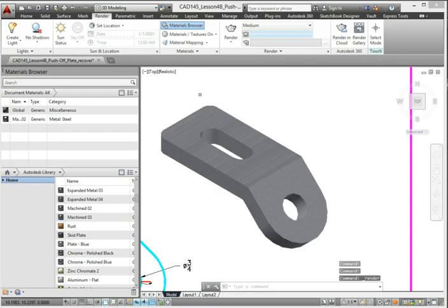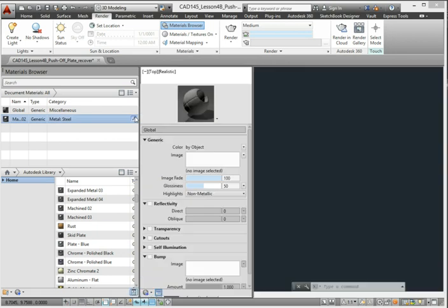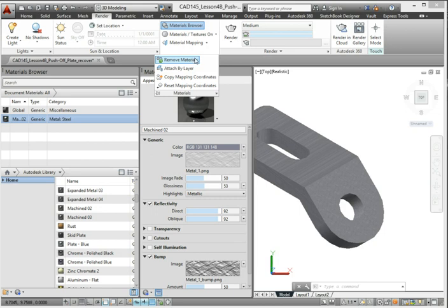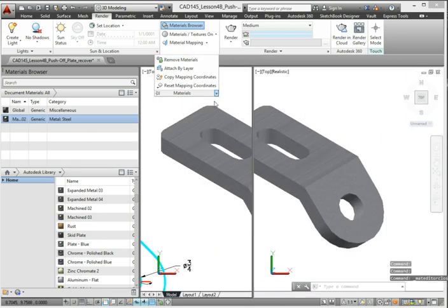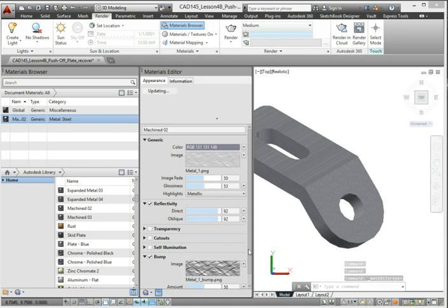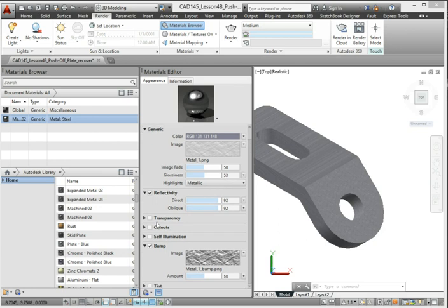Let's continue. If you edit the material settings, you'll get to the material editor. You can also get to the material editor here. We're clicking that arrow right there. Each material has a lot of features that can be customized. Too much to discuss here. One of the more common concerns is reflectivity when you add light. Because this will be reflecting the light, you might have to take it off sometimes in order to see your material. Right now, reflectivity is on.